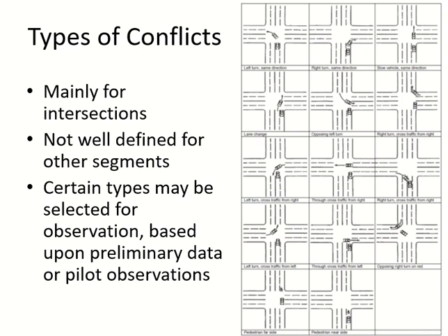In all these pictures you will see there are two vehicles involved, or a vehicle and a pedestrian involved. So wherever there is a possibility that two vehicles from different directions can be together at a point, that's a conflict. Or wherever a pedestrian and a vehicle can be together at a point, that's a conflict point.